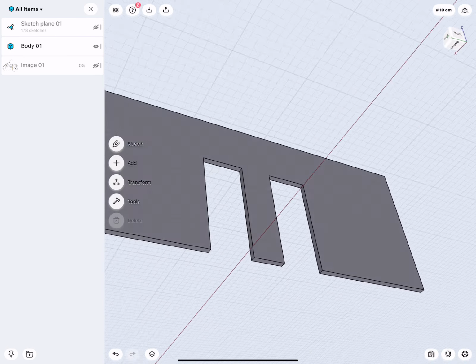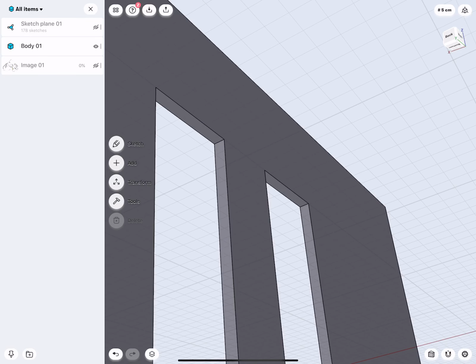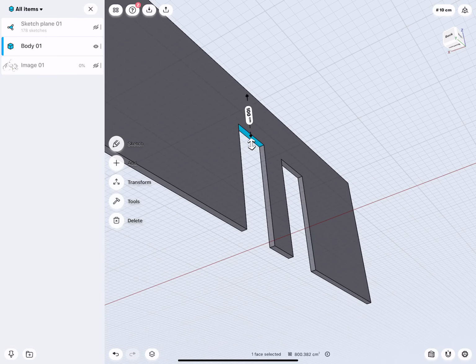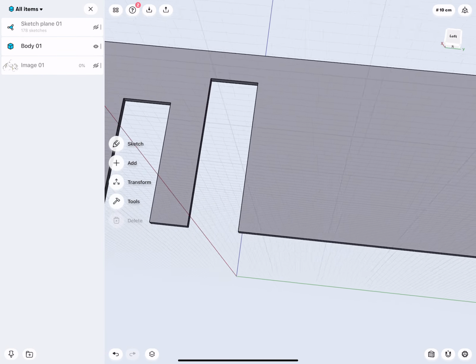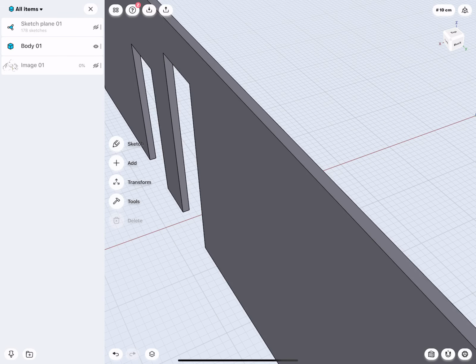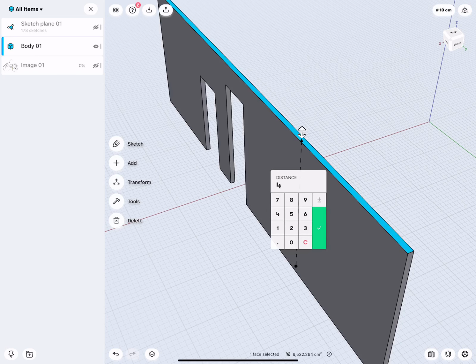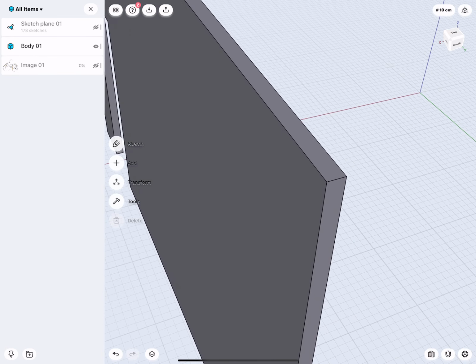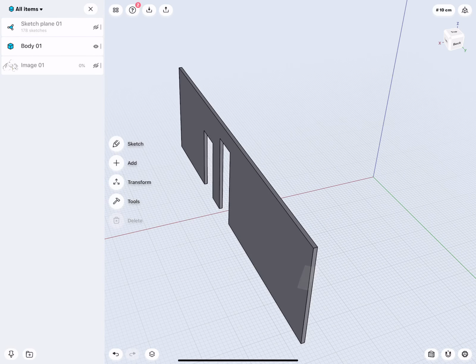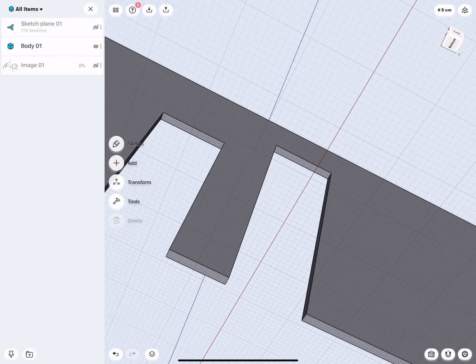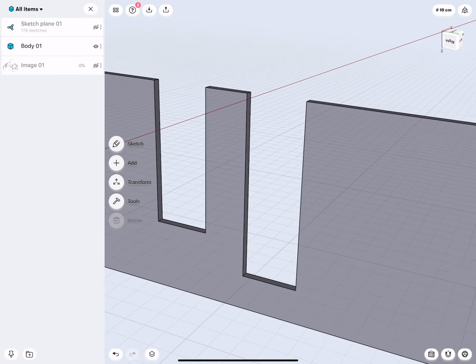I would like to show you a little bit of what push and pull is. If I select this, it tells you this is 100 centimeters from the top. I would like this distance to be 50 centimeters. So from the ceiling down, it is actually 50. What about the height of the wall? Instead of 3 meters, it should be 4 meters. So you see that you don't necessarily need guidelines. We can simply move everything via direct dimensions.